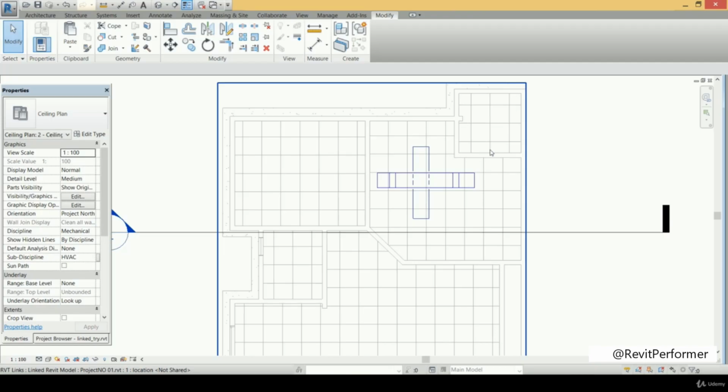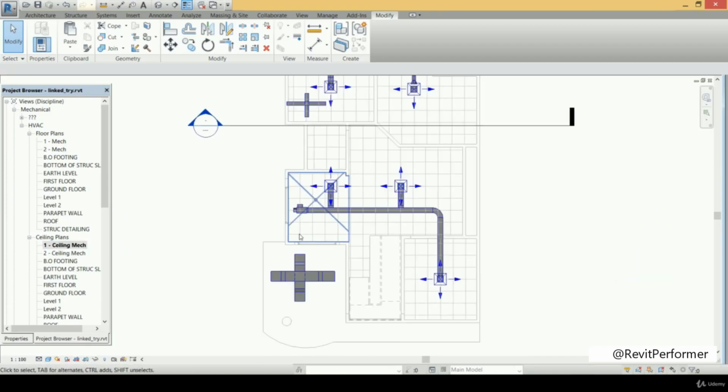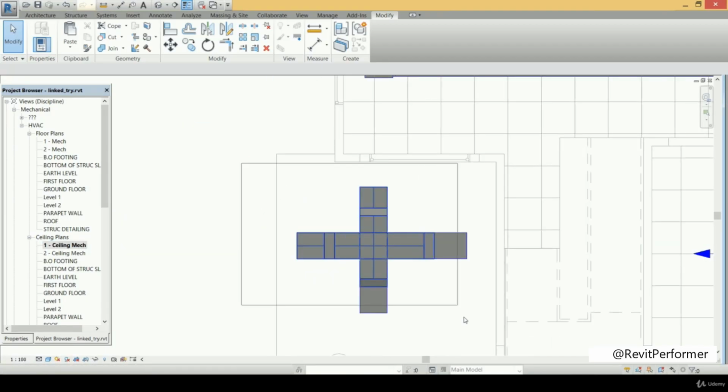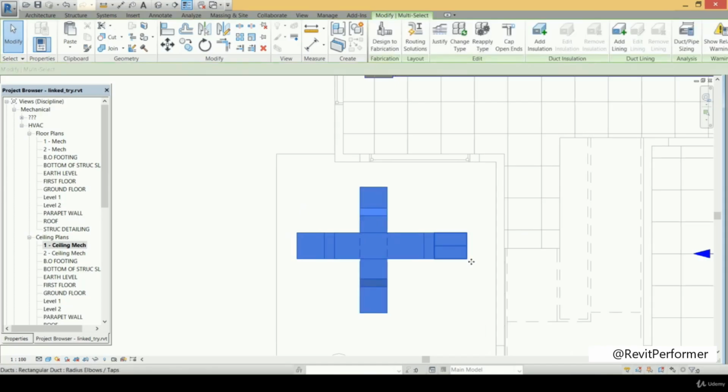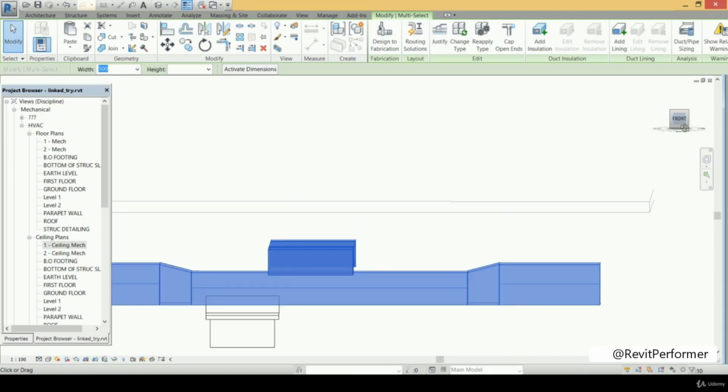But the 20% of reduction of the duct height gives us only 10 centimeter from each duct. So at that condition, we make the reduction process from the two ducts together to get the total height as we need. And for that, I have prepared that construction for you to understand it well. So when we go to the first ceiling, here you can see this is the case that I told you about. And when I select that part to see it in the 3D form, and press on the selection box, and now let's see it from another dimension.